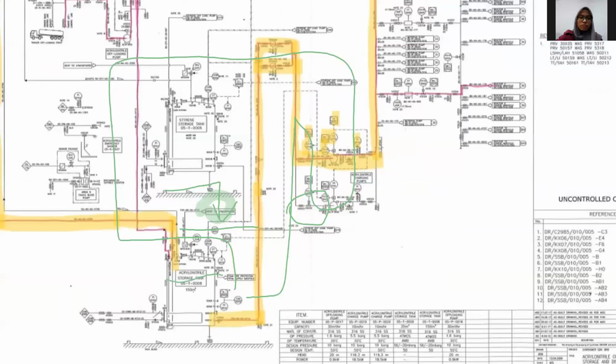Okay, so for the second step, first of all, ensure the chemical cleaning circulatory system is available and connected to the tank, and line up all streams involved for the second step of chemical cleaning.